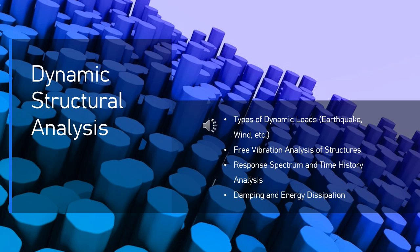9. Dynamic structural analysis. Damping and energy dissipation. In dynamic structural analysis, damping refers to the process by which a structure dissipates the energy imparted to it by dynamic loads, such as earthquakes, wind forces, or any time-varying excitation. Energy dissipation plays a crucial role in reducing the amplitude of oscillations, controlling vibrations, and ensuring the structural safety and comfort of the occupants. Understanding how damping works in a structure and how energy is dissipated is critical for designing systems that can withstand dynamic loads without excessive motion or failure.